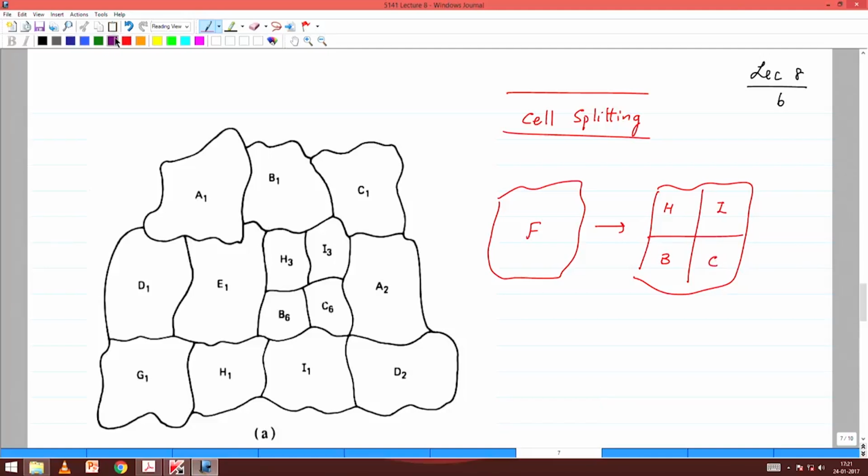Okay. Now just as a thought exercise, I could have assigned I here, could I not? Basically, I would also work. Instead of I I could have given H here, I could have given C here, I could have given B here. All I need to make sure is there is sufficient separation from any other cell that is using the same frequency. I could also have assigned F to any of those. Notice F was there. I don't need to leave off using those frequencies. I could use F in one of these, not in more than one. Any one of them could have been given F, and then I would have to find 3. But the concept has a huge impact.